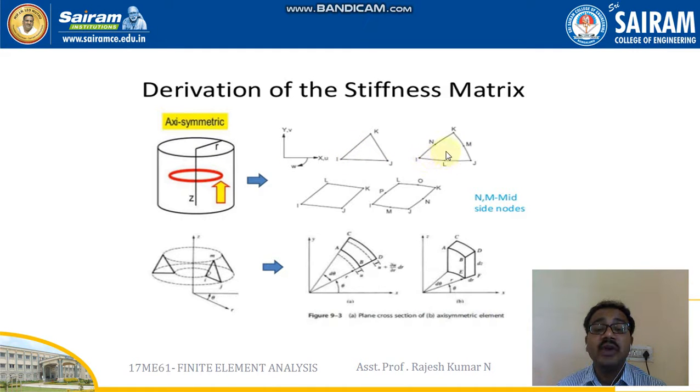In case of any other 2D element which has some complexity in its shape, you can go with more nodes depending upon the requirements. For example, if I'm looking at a 6-node element, I can go with I, J, K, L, M, N. And if it is a proper 4-node 2D element, I can go with I, J, K, L. And for a proper or improper rectangular shape, depending upon the shape we have, we can go with IJKL and MNOP.